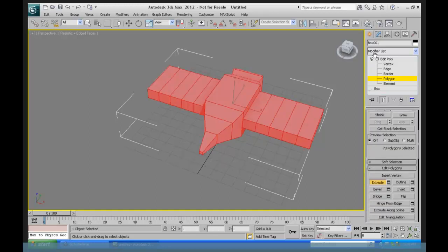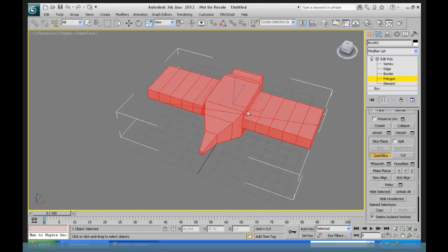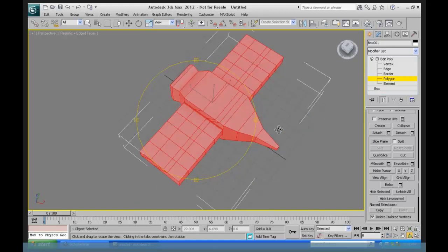Let's get that slice plane back. I think there's something called quick slice that lets me go like this and say that's where I want to slice. I set that, and that sets the slice plane. I slice it, and then I can move it, and I'll slice again over here. Bad technique here because I'm doing this in the perspective view, so probably things are a little bit wacky. See, what did I say? There it is, it's wacky.